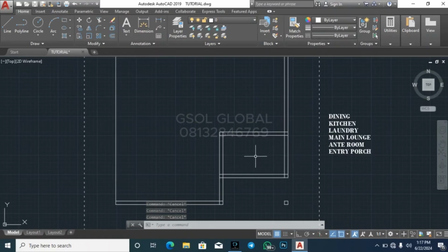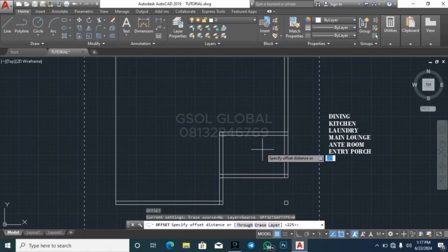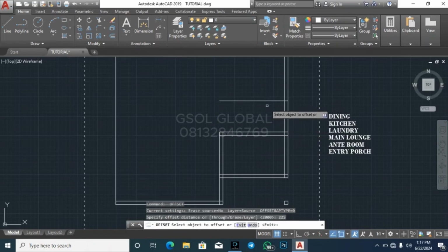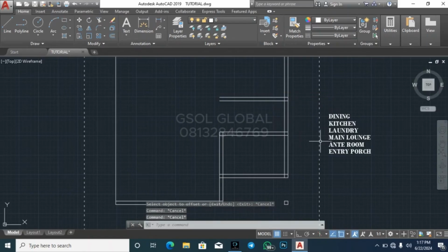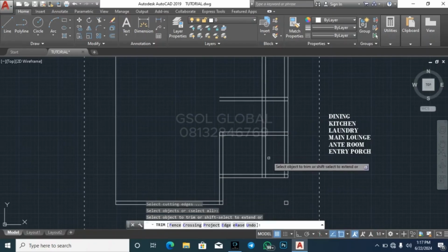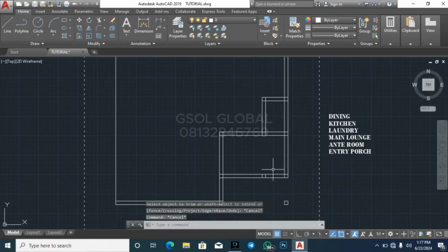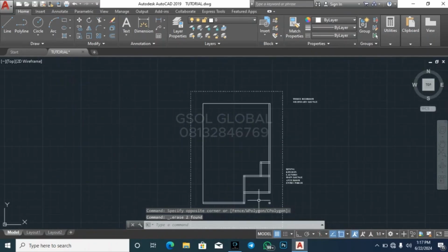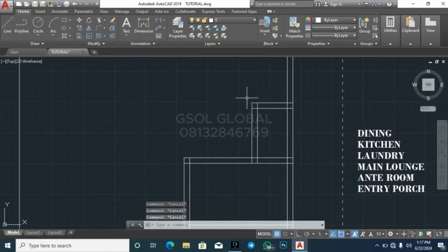In your ante-room, you consider a lot of things. All right, so for my ante-room, I want to have an easy access to where we have my visitor studio, so I can make an offset behind it, 2 meters. All right, 2 meters. Then we have 225 for the block work, and then offset of width 1200. So 225. So I can go ahead and just trim this, trim and trim. All right. So actually trim that. So we're having our toilet behind it.